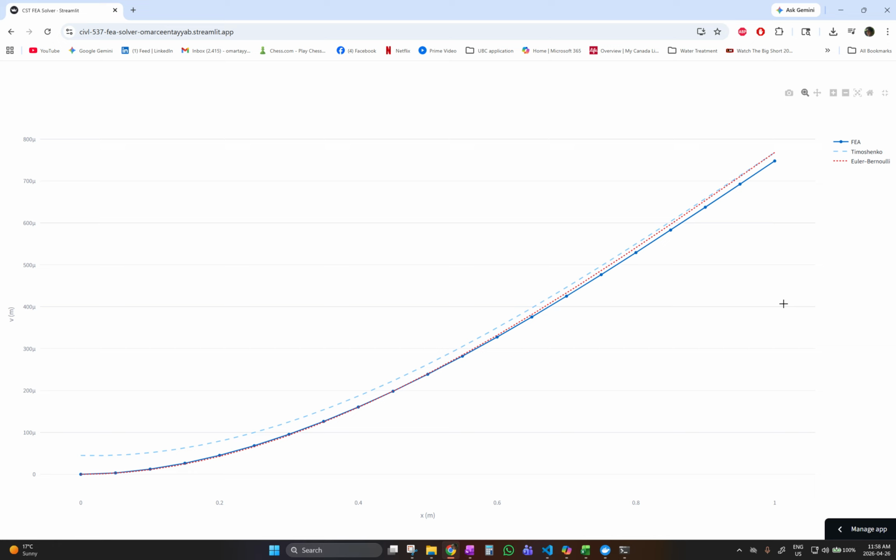So you can see almost a step change in the shear, because the max shear point is basically not captured at all by Euler-Bernoulli. Then shear becomes less of a factor as you move away from the fixed nodes, and the two solutions come together to be basically perfectly equal, because shear stress is zero at x equal to L. The FEA solutions do a really good job.